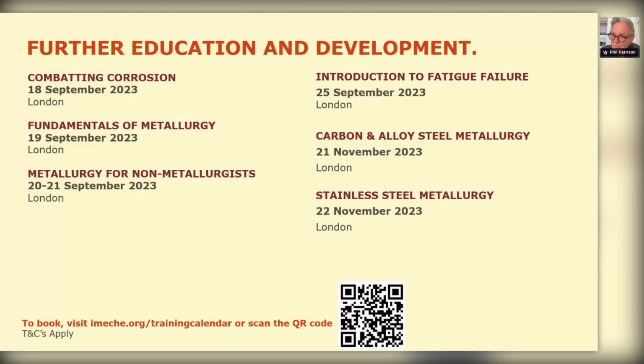Yeah, but in danger of further waffling, we have a second question on fatigue, which is: is fatigue only a consideration when cyclic loads exceed the metal's proof strength? It's below the proof stress. Basically, the loads are below. If you get it above the proof stress, you are actually plastically deforming the material. When you plastically deform it, you're removing the strain energy in the material. The buildup of strain energy is responsible for initiating the crack.